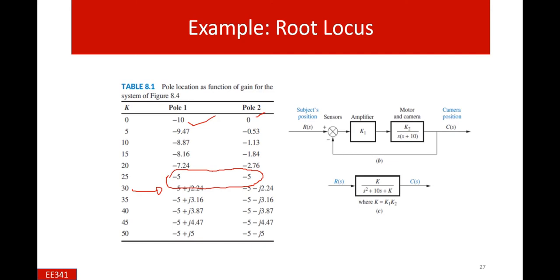This pair and its behavior is very important to understand the root locus. This pair changes accordingly, and the lengths are equal if we manipulate the distance values and change the values of K.